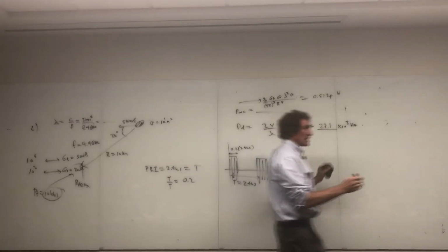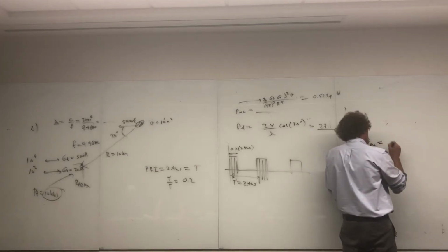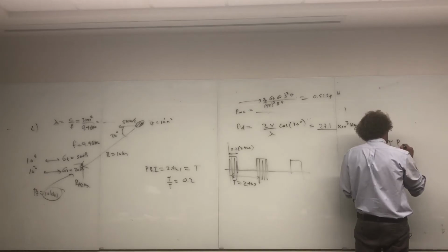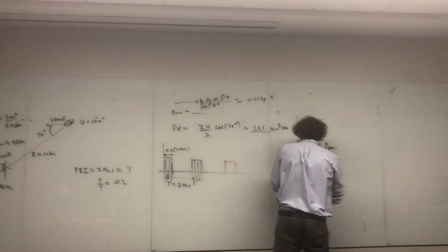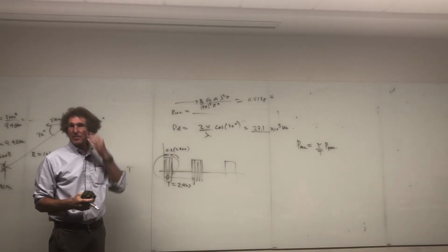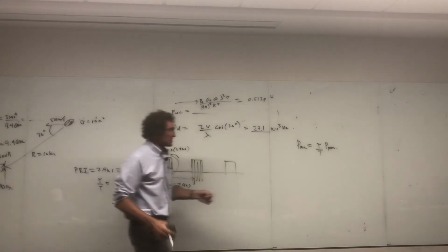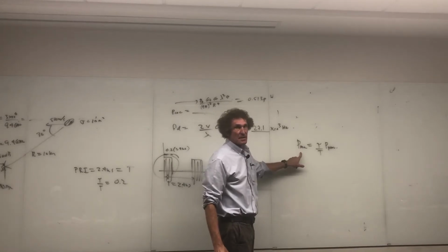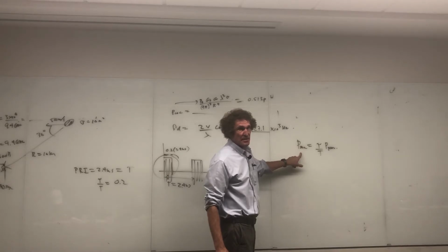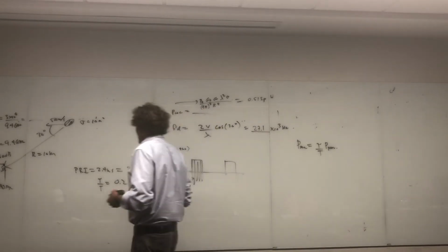And if you think about that, average power in a waveform would be equal to tau over T times the peak power. So during this part of the actual transmission, that's when all the peak power is being transmitted, right? Then it goes to 0. So this is the average power during that period. Y'all follow me on this, class? Now that's usually what's done. He doesn't break it down this way in Dr. Wentworth's book, so just something to keep your eye on.